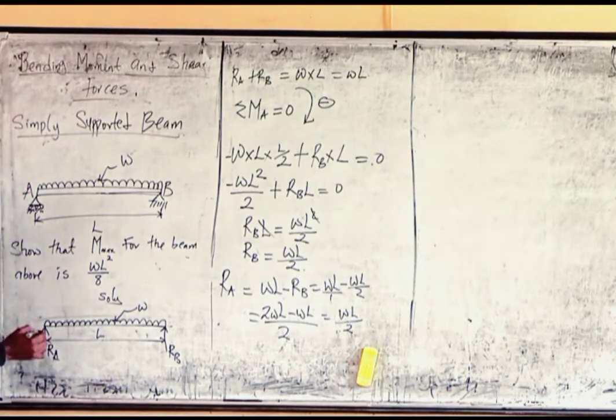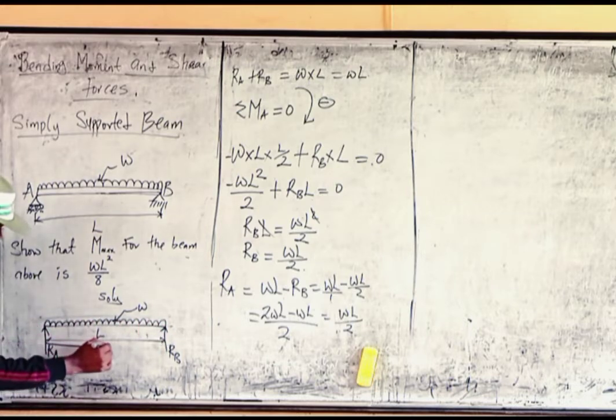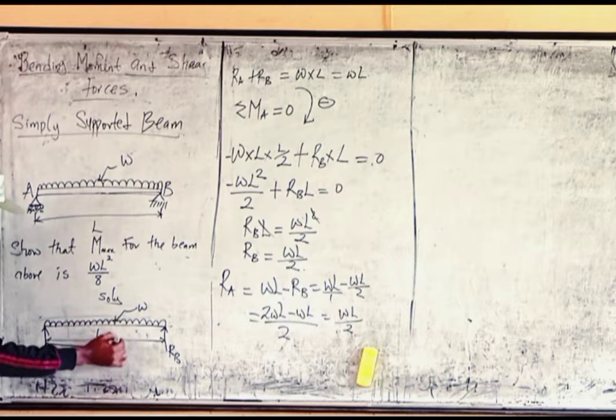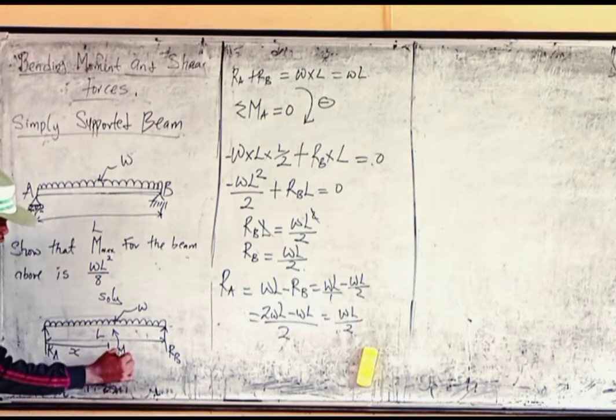Okay, let's develop an equation so that we'll get our shear force to be 0. We take a little distance from any of the ends and call the distance x. Then let's take moment about this point x. I'm going to take moment about that point x. Okay, let's say moment at x.